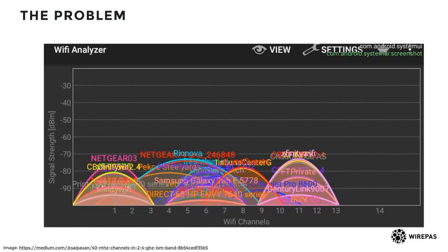You get lots and lots of access points out there, and all of a sudden the noise floor of the system is quite high. And when you're operating with low power battery operated devices like we do in the IoT space, that means that you need to do retransmissions, you need to transmit at higher powers, and sometimes you can't even get through because the noise is so high. And so you need a system and a network that is very resilient to that.